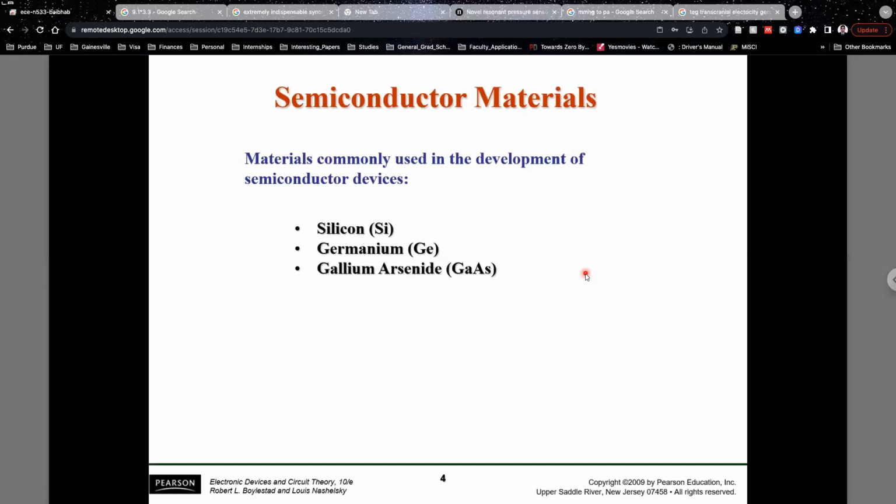So because of this impurity over here, what you have is the non-existence of a bond, or there should have been one electron over here with which it will bond with one other electron of the silicon, but that is not present. So this is the non-existence of an electron which should have been there if everything was ideal silicon.